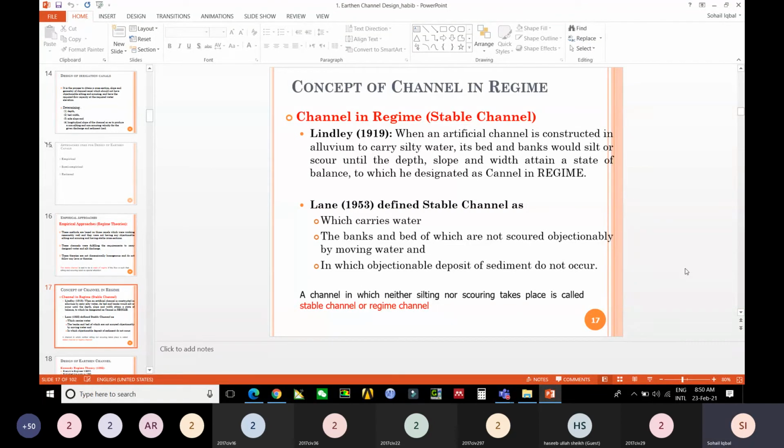Okay. So here are the theories of Lane 1919 and Lane 1953. What is a Lane? When an artificial channel is constructed in alluvium to carry silty water, its bed and banks would silt or scour until the depth, slope and width attain a state of balance, to which the design is a canal in regime. So he explained about the stable channel or the regime.